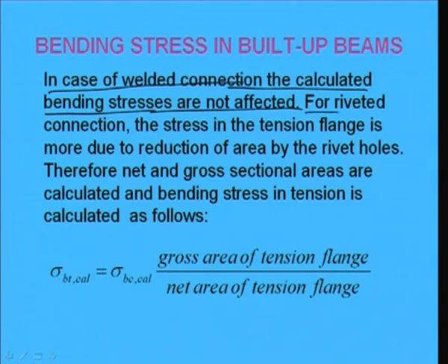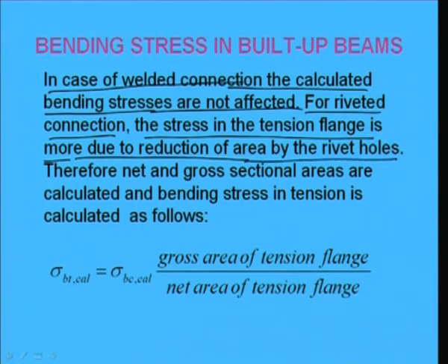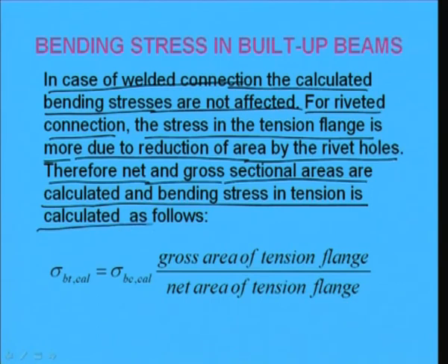But for riveted connection the stress in the tension flange is more due to reduction of area by the rivet holes. So, stress will be more. Therefore, net and gross cross-sectional areas are calculated and bending stress in tension is calculated as follows.